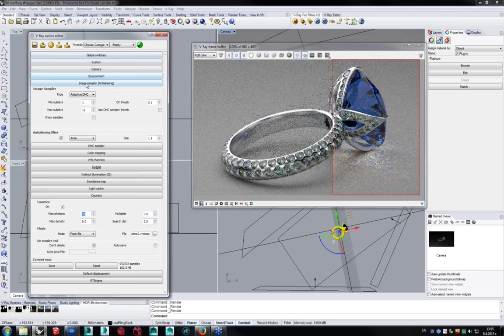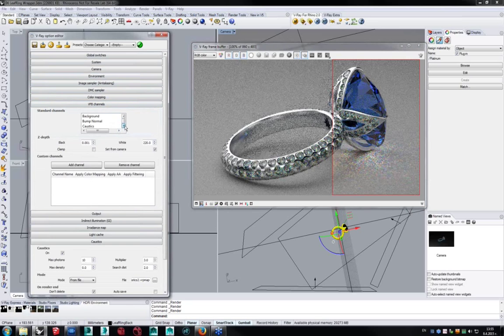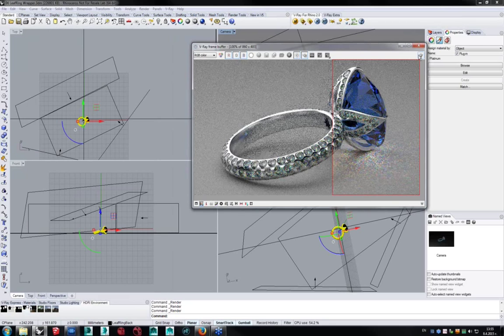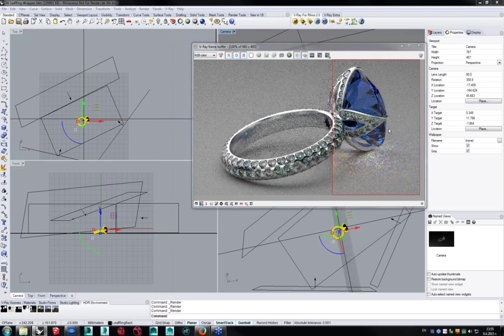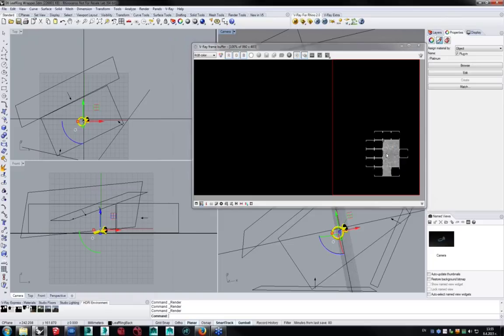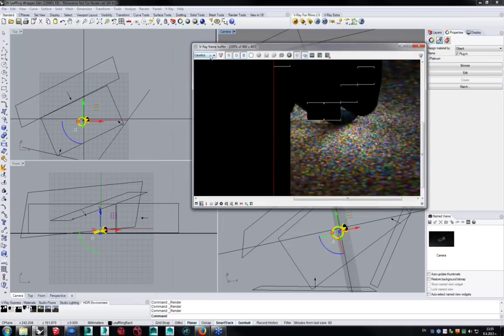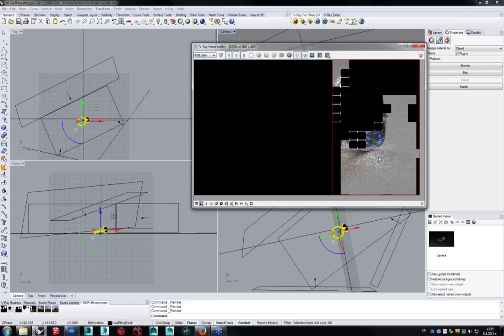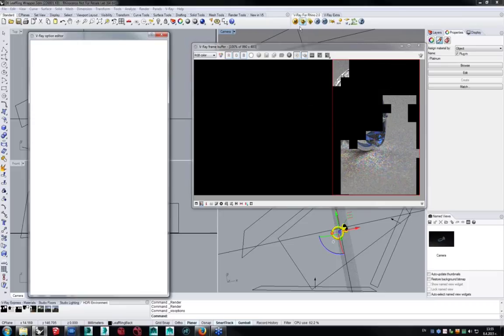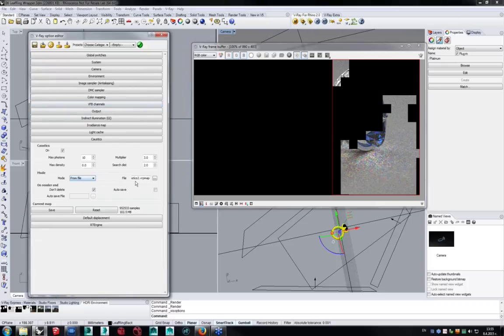What you can do is go to the VRB channels and select the caustics render element. So let's render with it. And now I think I'll have caustics, which will be very useful. I can do some post compositing with that render element, and I can determine how strong and pronounced those are. Of course, this is not very realistic currently. This is just a way of controlling those caustics. That's my point. And you can save the file.